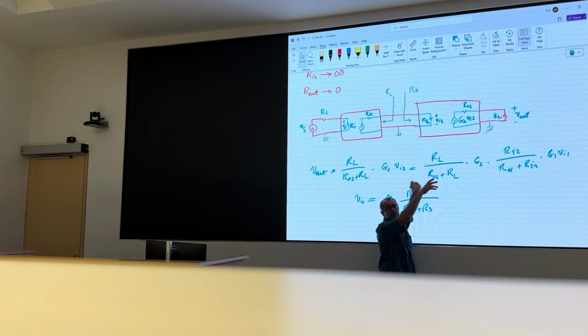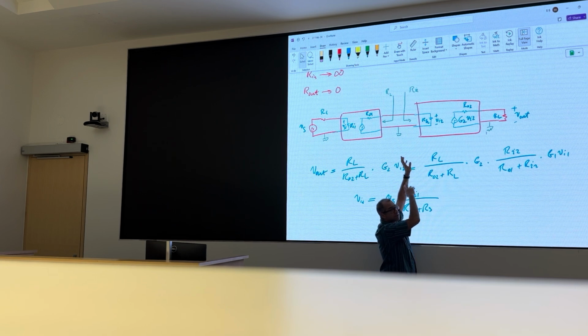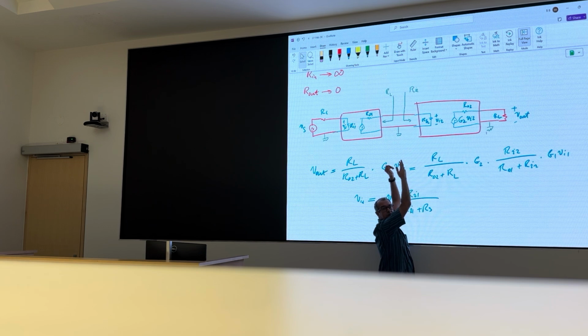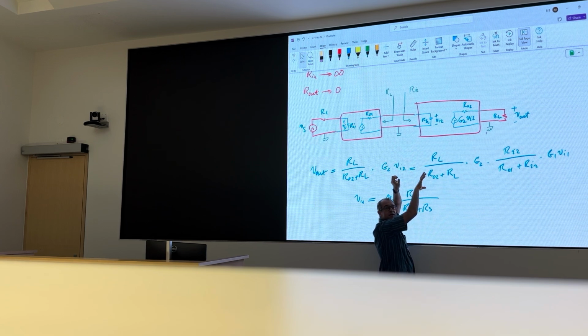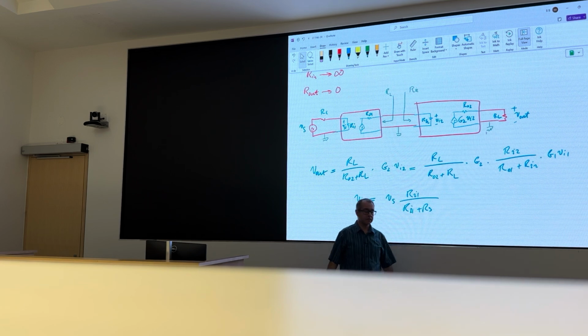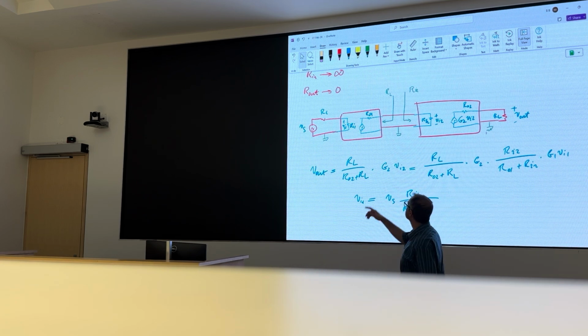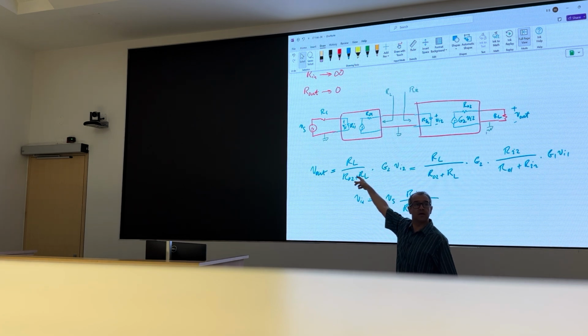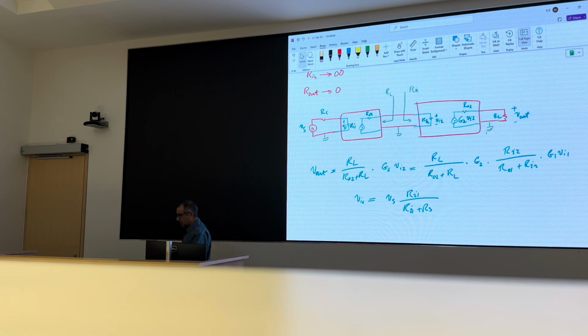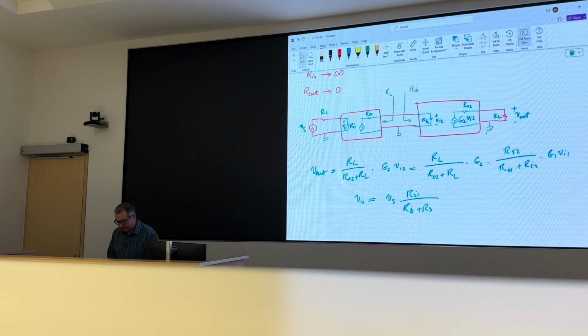So the impedance at the node, or resistance at the node, is that I cut my circuit from that node, both of those lines, and I attach my test source and measure how much current is coming from the test source. That's my equivalent resistance. Now I can do it for the guy on this side too. Rs is that input source, so Vsource, Rsource. Okay, so let's do this for a couple of circuits and see what we learn.